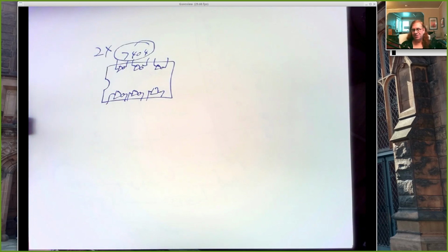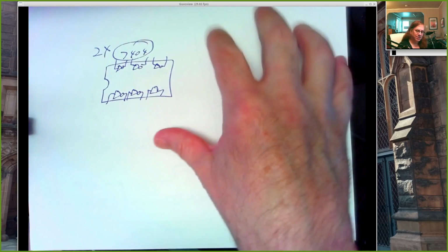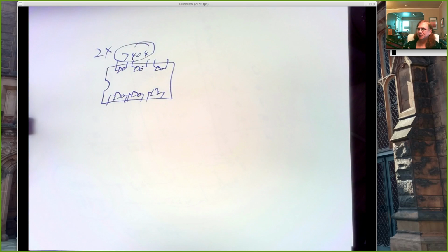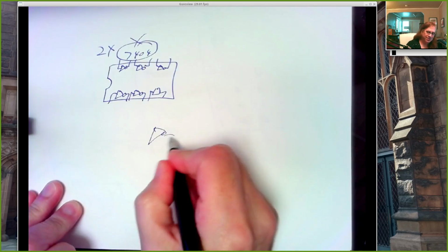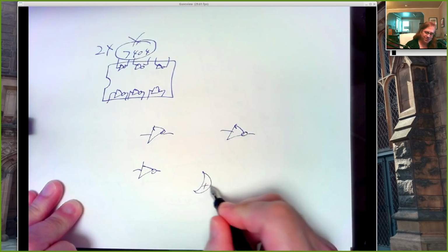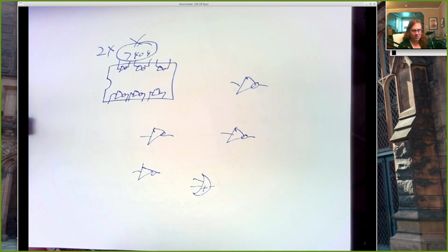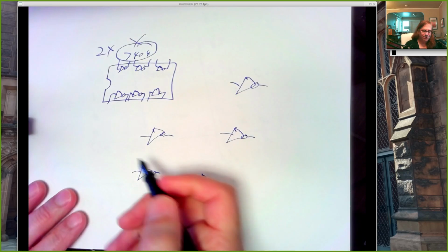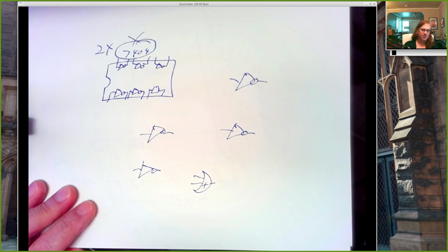And maybe in Tinkercad it's easier to totally replicate your circuit from one lane to the next and just have 3 copies of it. But if you're doing your schematic first, your schematic has no notion that you're using a 7404. It just sees that you've got some AND gates and some inverters and some OR gates and so on. And you build your schematic, and then once you've got your logic diagram with your logic symbols for gates, then you say, how am I going to build this in Tinkercad? And you say, well, each of these is going to have to be a 7404.